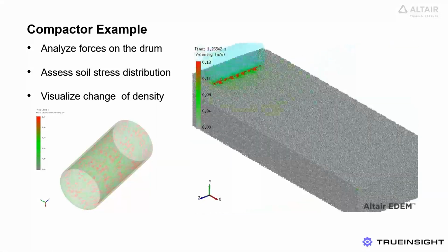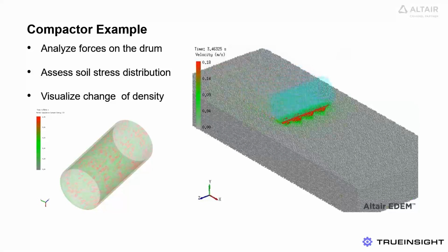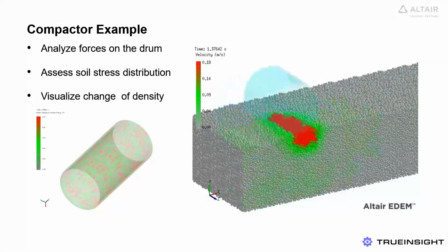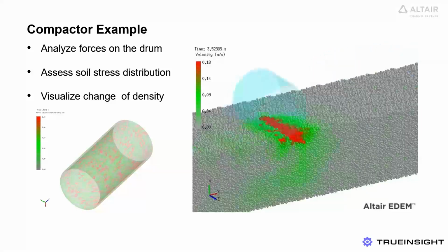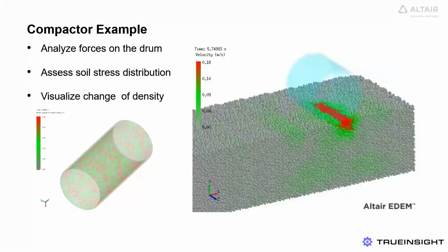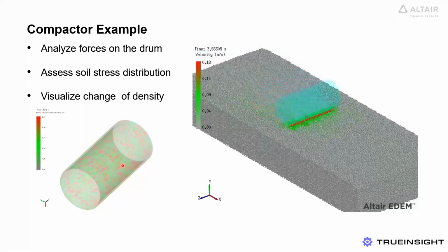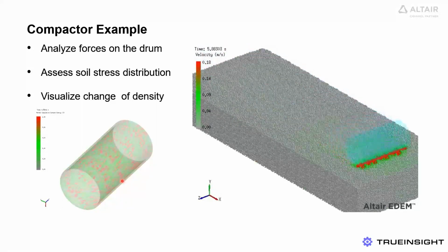It's also possible, as in the dump truck example, to analyze regions of the roll that are more likely to wear and how the stresses are distributed along the roll. And that tangential energy that's been absorbed by the surface of the roll is visualized in the bottom left.